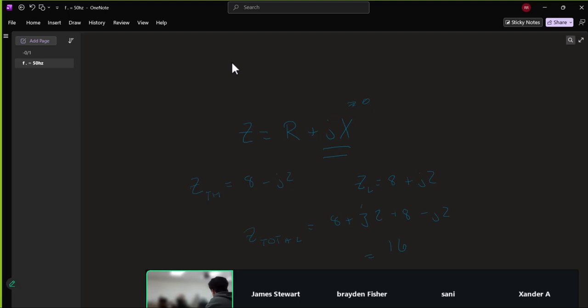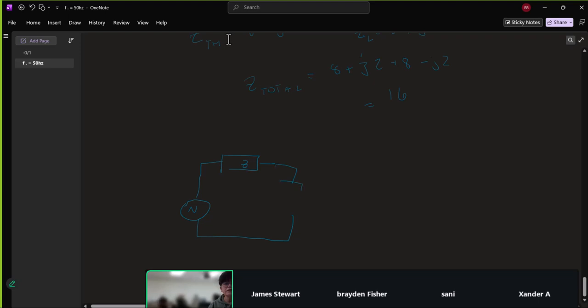Well, it is, if we're talking about Thevenin and a load. Because when we're talking about Thevenin, what we're saying is we have our circuit and our impedance, and we're going to put a load in here, Z load, and we want to know what the impedance of that load should be in order to get maximum power transfer to the load. And we get maximum power transfer when these two things have the same resistance, so we want this to have the same R as this, and we'll get maximum power transfer when we get rid of all the reactance in the entire circuit.